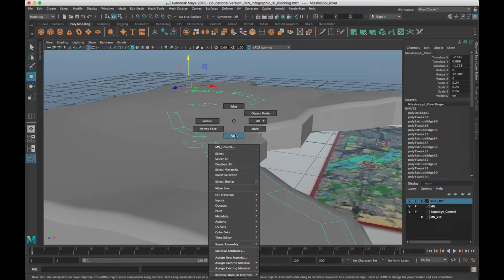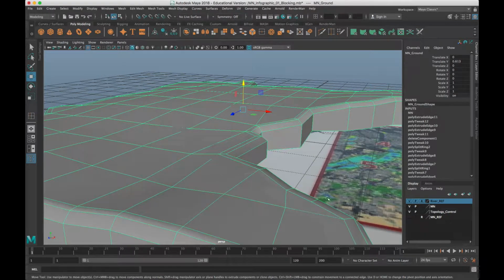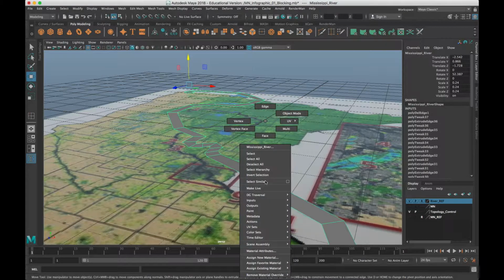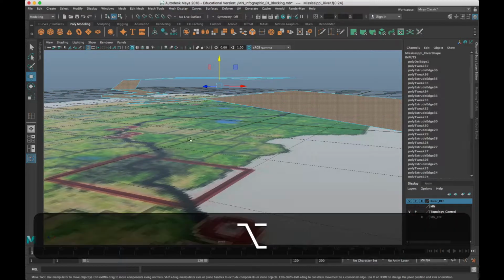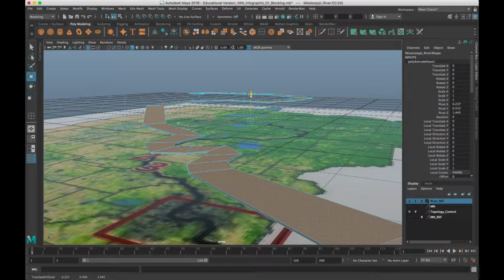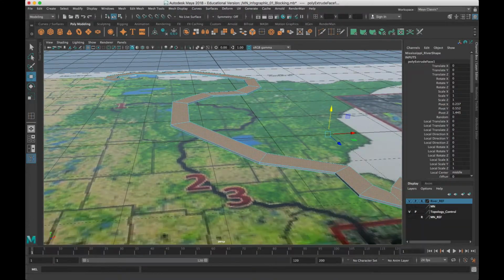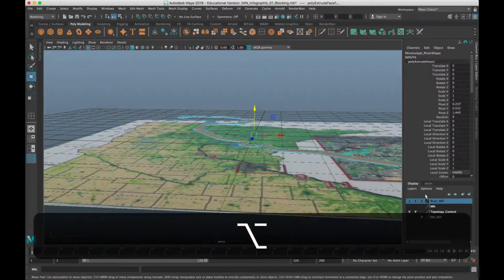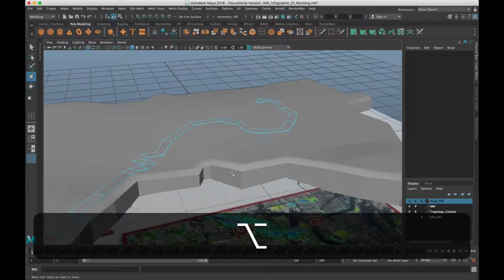And so the way that I'm going to do that is select the faces. Let's see. I'm going to get rid of the river here, or the state. There we go. So select the faces, and I'm just going to extrude it up ever so slightly. So hold down Shift, left click and drag on the up move arrow, and something just like that. Well, mine didn't work. I've got some thickness. I can turn the state back on, and you can kind of see that it's there.